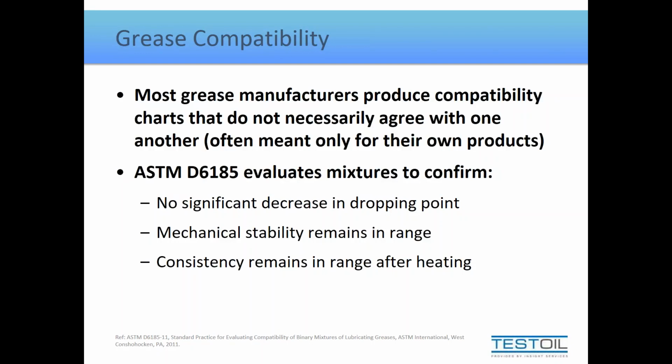And these are done at different mixtures. You know, typically they're done at 10-90, 50-50, and 90-10% mixtures. Sometimes they're done at 25-75 and 75-25 as well. But this gives you a broad spectrum, and of course you have 100% of each grease measured as baseline references on either side of the compatibility testing. So there's quite a bit involved with grease compatibility testing.